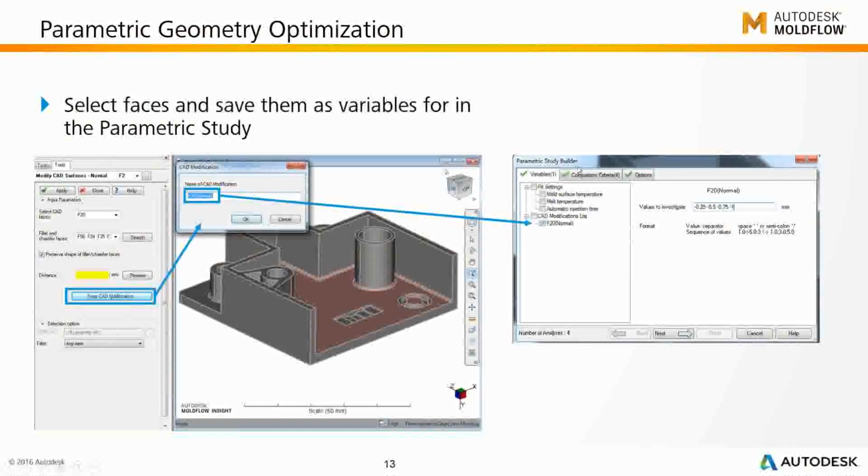And when I go to my parametric study builder, which is a variation of our design of experiments builder, I can start giving that a set of deformations. So instead of just looking at one variation that I made manually, I can select this particular set of faces that I want to modify, and I give 4 different modifications to it. So I create 4 different permutations of this model. I can do this for several faces, and create all the permutations of, let's say, 2 or 3 different combinations of modifications that I selected.